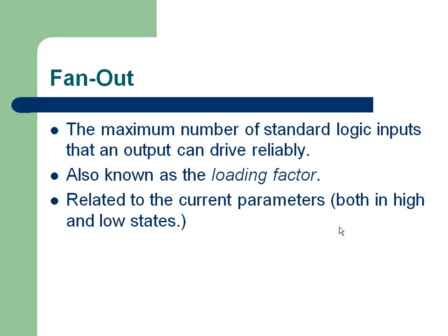Clock trees are used very carefully, because they occupy resources. They take more area on silicon. If you are running, let us say, a metal 4 clock, that will be very wide. Got it? So you have to use it carefully.